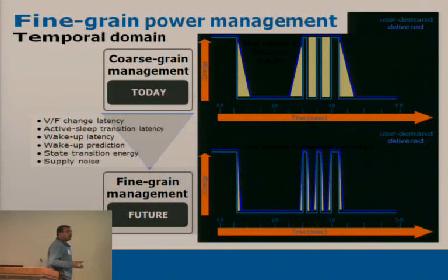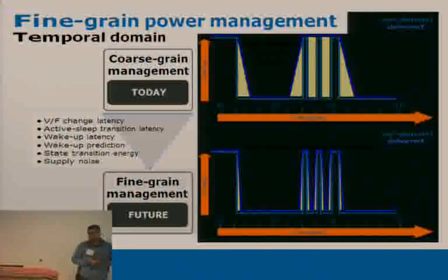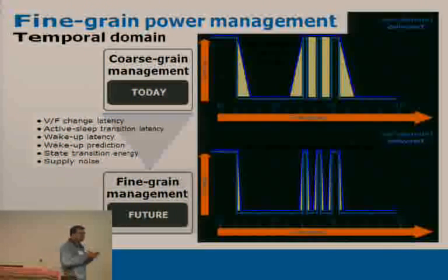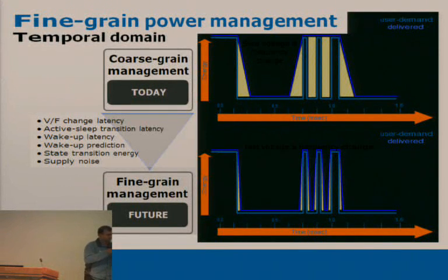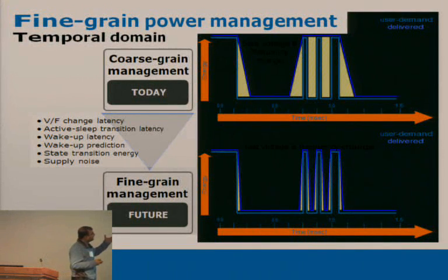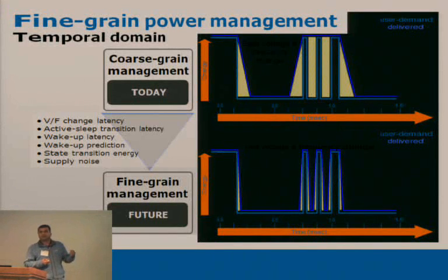So idle power is bad, standby power is bad. We all established that this morning. Even within a so-called active operation from a chip designer point of view, from a microprocessor chip point of view, today we have the OS monitoring the load, with 15 millisecond kind of ticks, right? So wake up and you shut down on 15 milliseconds. That's too long, because you can waste a lot of power in 15 milliseconds if you're not doing anything for a CPU.